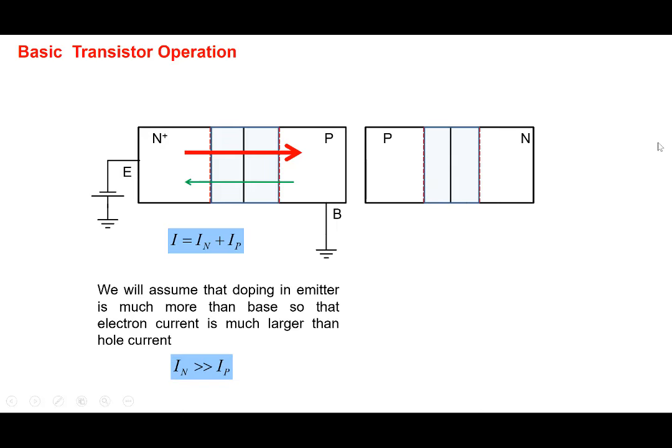Okay. Let's look at another junction here, P and N. In this case, the other junction, note again, there's a depletion region and all that. This particular junction, we reverse bias it. So we apply a positive voltage to N, and P type is ground. So it's a reverse bias junction. And note that in a reverse bias junction, the direction of the current has to be from N to P, from right to left here.